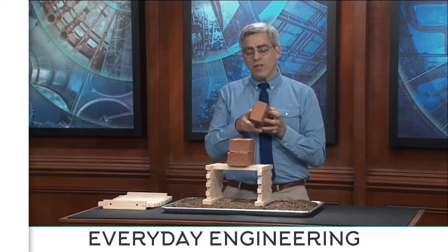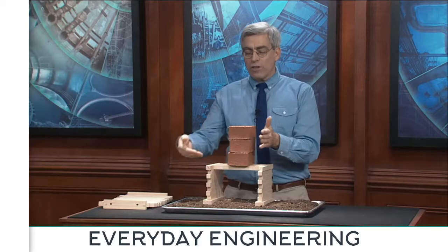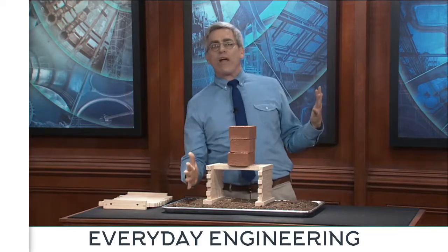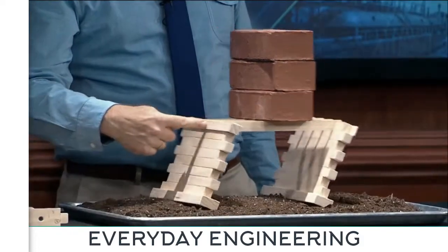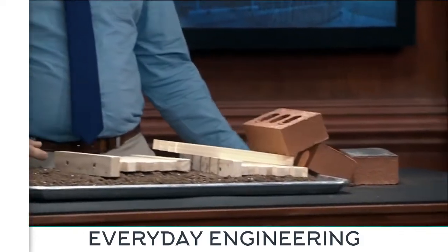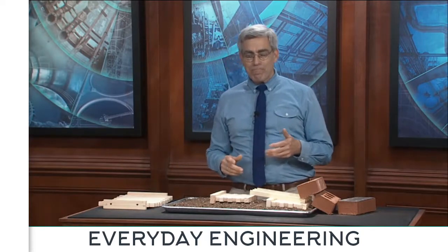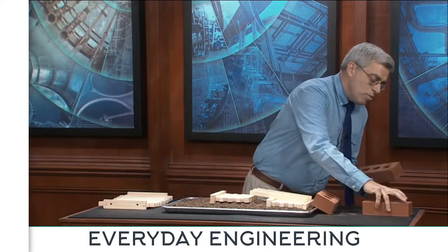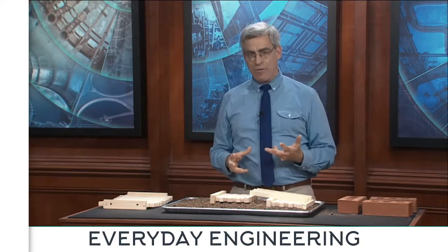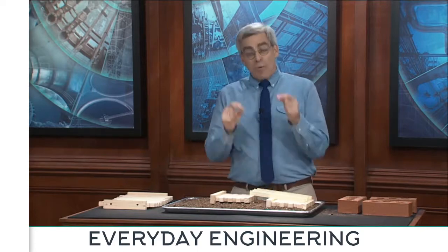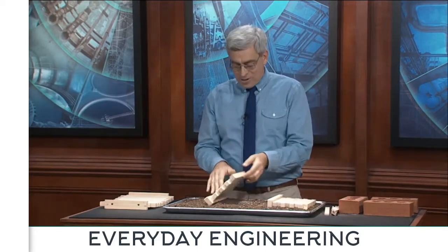But what about horizontal wind load? What happens when we get a large lateral load applied by a wind striking the face of the building? Well, as you can see here, the arrangement really isn't particularly stable. So the bearing wall system needs some sort of additional augmentation in order to be able to carry those lateral loads. But we can add that augmentation quite simply by adding the other two walls of the building.